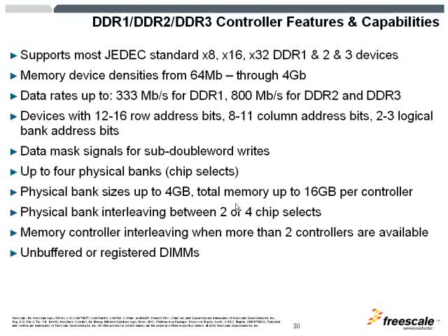The interleaving between the 2 chip selects or 4 chip selects are available. Memory controller interleaving when more than 2 memory controllers are available. That means if the device that you're using has more than 2 memory controllers, interleaving between the 2 controllers are also provided. Unbuffered or registered DIMMs are supported as well.